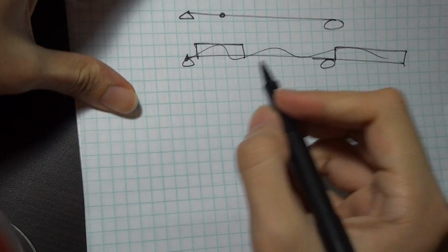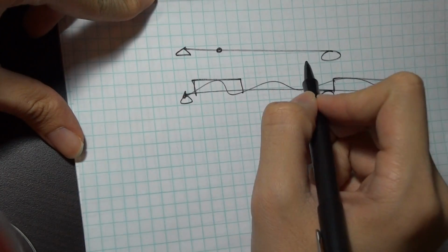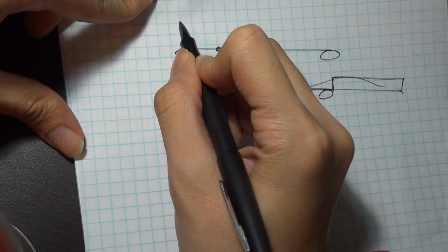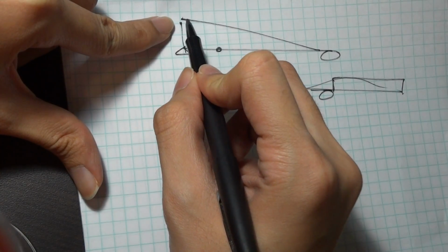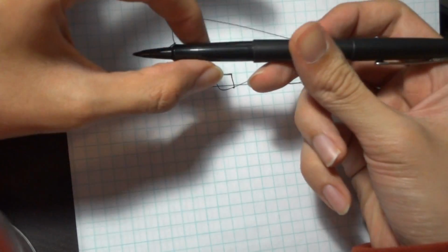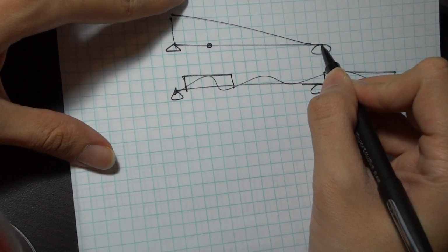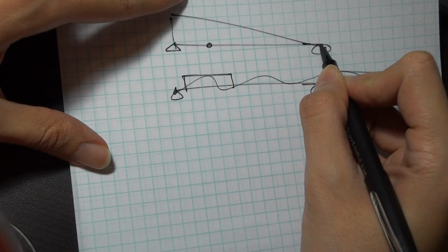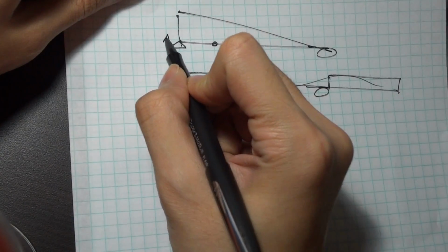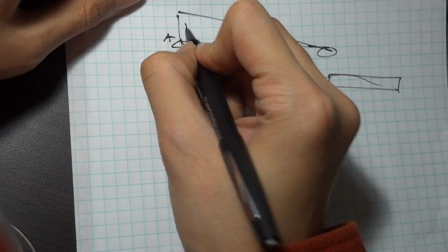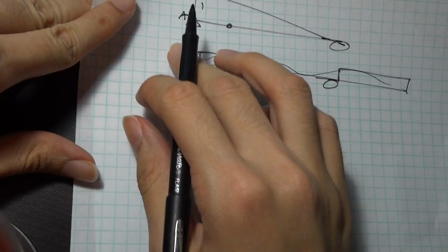Let's say I'm interested in the reaction at this point. If I wanted to generate my influence line diagram, all I would have to do is take this point and lift it up by 1. This section has to remain rigid, so I'm literally lifting this beam up by 1 at this point. I'm rotating it about this point because I have to maintain my original boundary conditions. A reaction is a boundary condition, and this is my unit influence line diagram for the reaction at this point. So if I want to find the reaction, I lift the reaction I'm interested in up by 1. It doesn't matter if it's at the end or if it's in the middle.